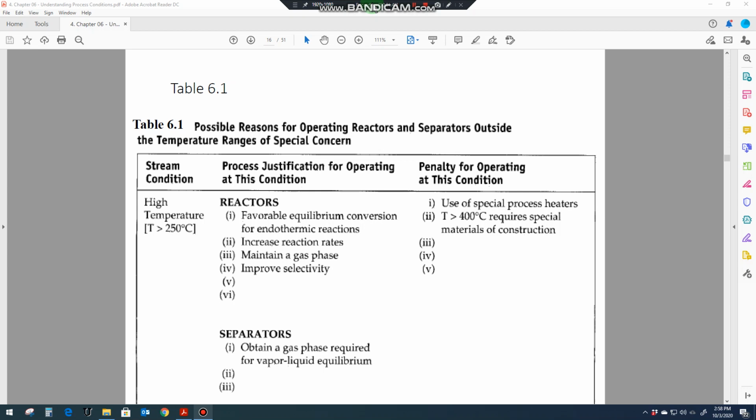And then we talked about the impact of high temperature on the material strength, and we saw that the material strength would be significantly decreased if we go beyond 350 degrees centigrade. And we tried to solve some examples to see the material strength effect due to the increase in temperature.